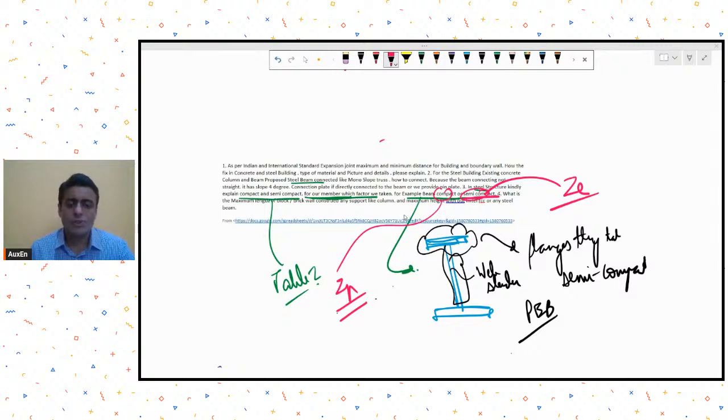But then it is also saving you on costing. So they might increase the web depth to take care of that extra 10-12% lost, and they try to arrange their section accordingly, which is the most optimized section. So usually what I have seen is that they try to go for a semi-compact flange and slender web. I'm only talking about the sections that are usually used in these pre-engineered industrial sheds. Okay.